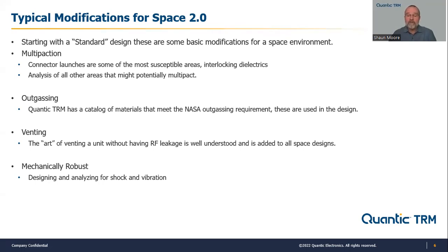So we have to make sure that the vents are large enough, and that there's no trapped area anywhere in the assembly that can hold the air in and slowly let it out later on. You want a good sized vent, and enough of them, so that the entire volume of air inside the component can be released and dissipated while the satellite is still on its ascent, and not continue to leak out gas once it's on orbit.